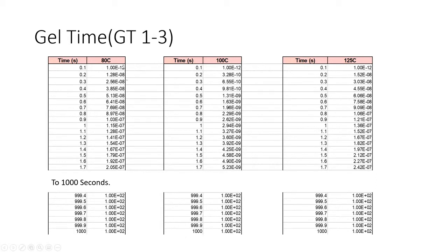You can use 80, 100, 120C for maybe a fast cure material, but you may need to increase the temperatures to get a profile that cures within 1,000 seconds. So we really slow things down and use lower than typical molding temperatures, because remember, the path of the material through the mold starts in the screw and barrel, and that's at just slightly above room temperature.